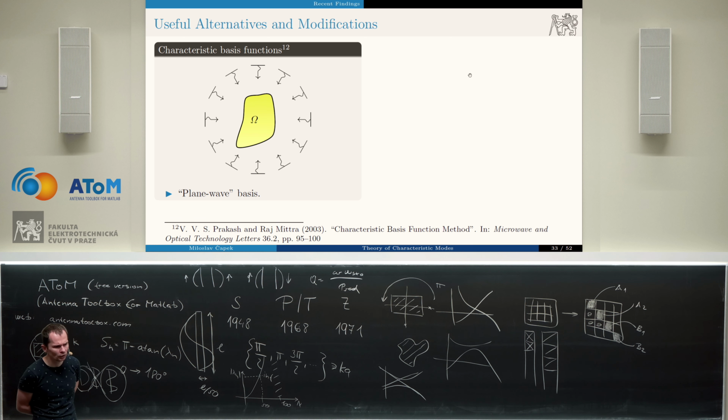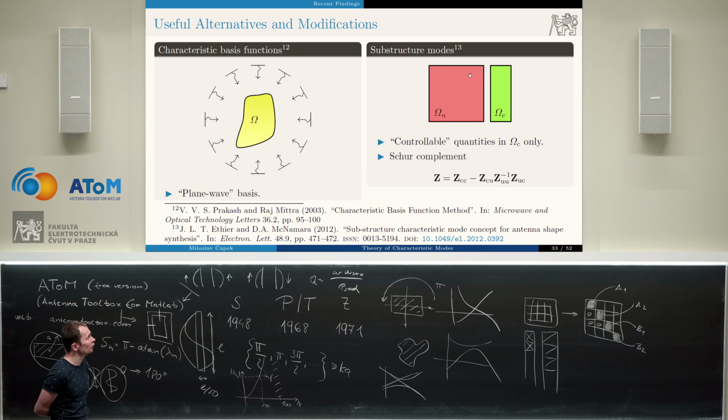I mean that I have, for example, a loop, and I am reducing the algebraic problem not only for a feeder here and a feeder here into a matrix of 2 by 2, but I do it for an incident plane wave for this one and for this one, and I use many of them. And basically then I employ the same reducing scheme and get new matrices. So this is one possibility.